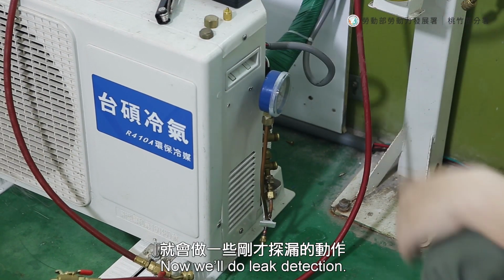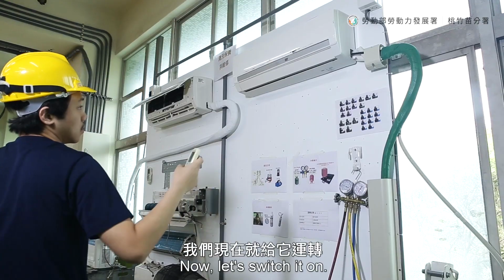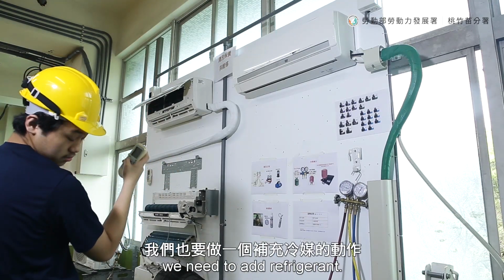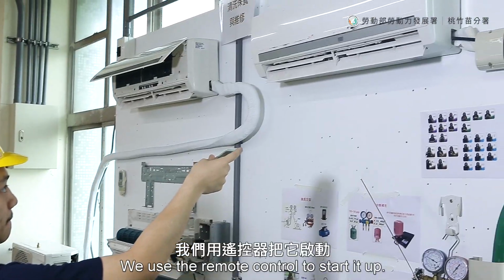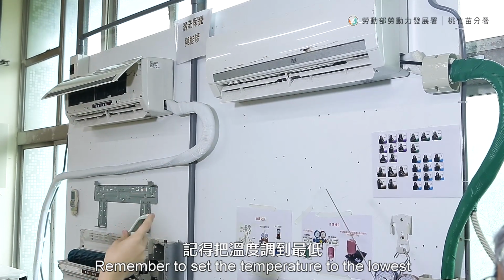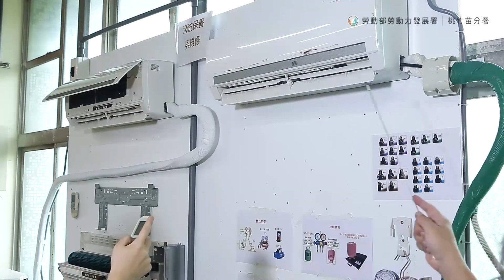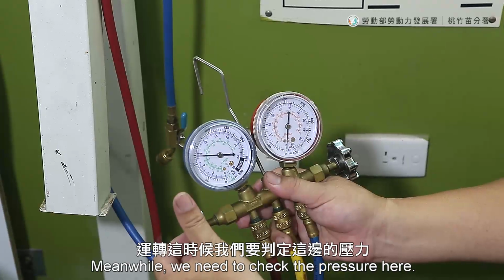Now we'll do the leak detection. Now let's switch it on. If there is insufficient refrigerant, we need to add refrigerant. We use the remote control to start it up. Remember to set the temperature to the lowest and the fan's speed to the highest. Let it continue to run. Meanwhile, we need to check the pressure here.